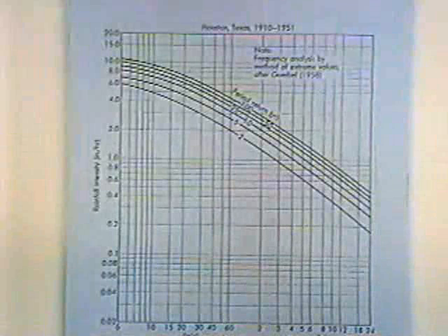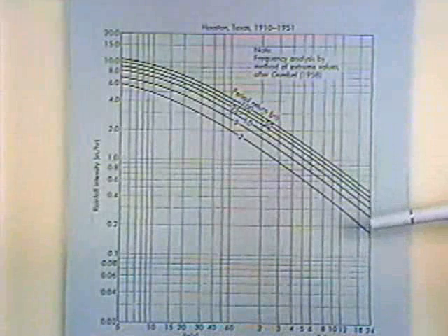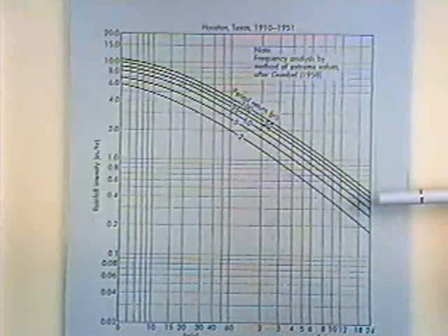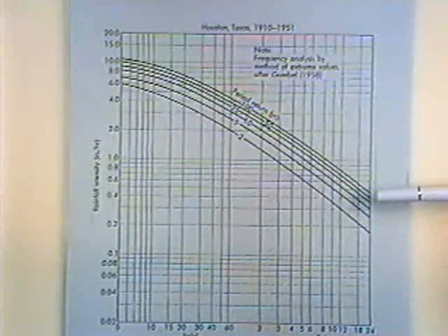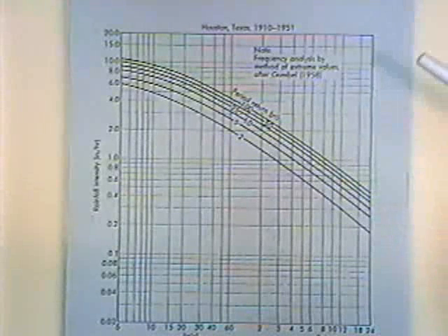And we often use design storms, and well, here's some rainfall data. This is the city of Houston, and cities will have this type of information which they provide in their drainage criteria manuals. I've never checked at Fort Hood. I would assume Fort Hood has a drainage criteria manual that's used to size all of the drainage facilities on the base.